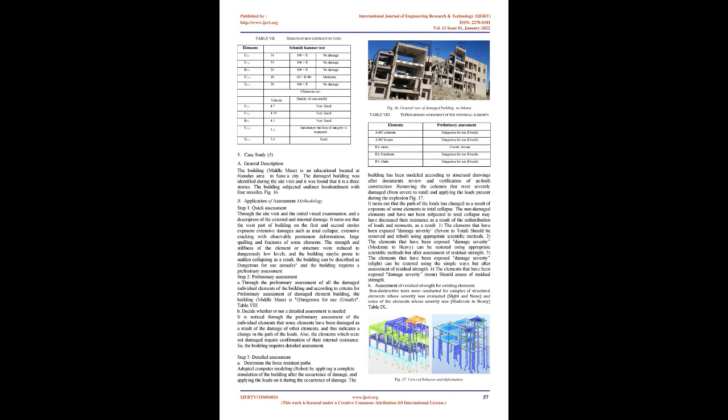Non-destructive tests were conducted for samples of structural elements whose severity was evaluated as slight and none, and some of the elements whose severity was moderate to heavy. Non-destructive tests, Schmidt hammer and ultrasound test, were used to ensure the quality and resistance of concrete elements after damage. Table 7. Through the results of the non-destructive tests in Table 7, it turns out that the quality and resistance of the elements meet the design requirements after being damaged, except for the beam B27-2, Fig 15.